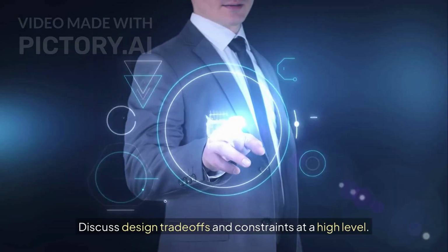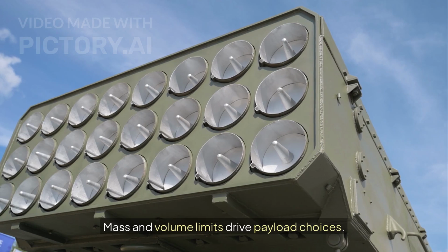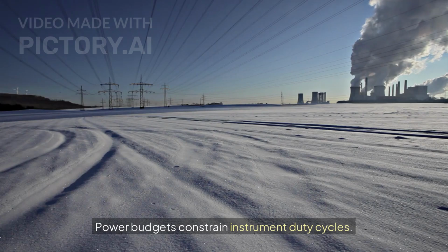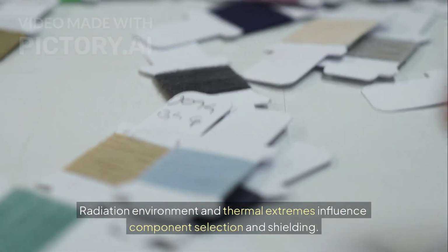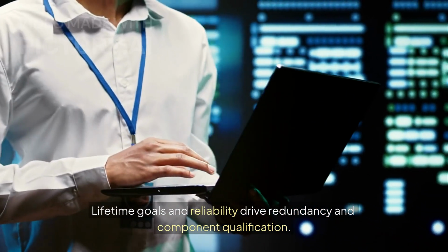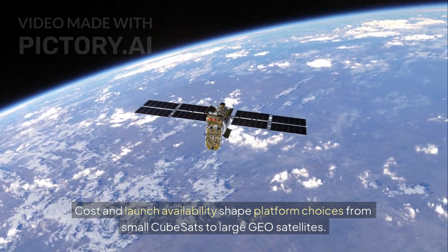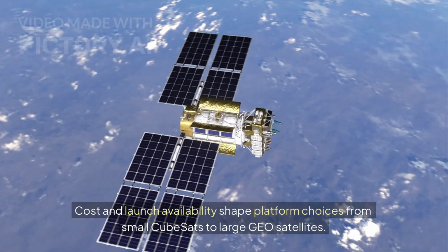Discuss design trade-offs and constraints at a high level. Mass and volume limits drive payload choices. Power budgets constrain instrument duty cycles. Radiation environment and thermal extremes influence component selection and shielding. Lifetime goals and reliability drive redundancy and component qualification. Cost and launch availability shape platform choices from small CubeSats to large geosatellites.